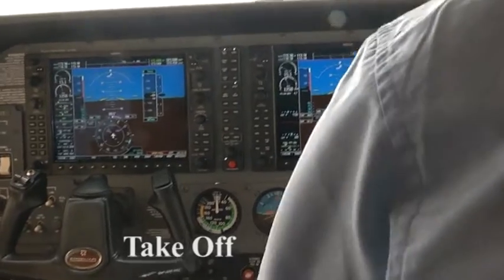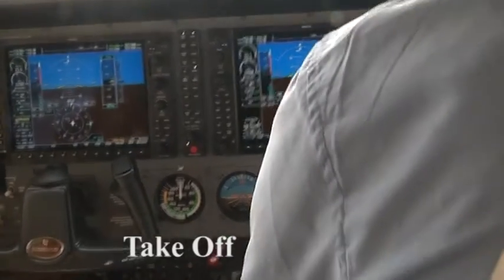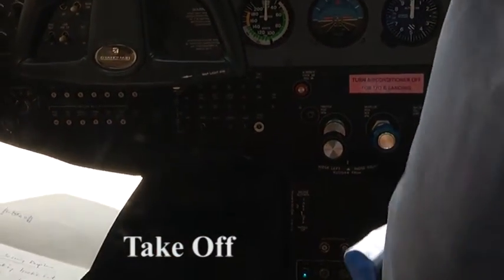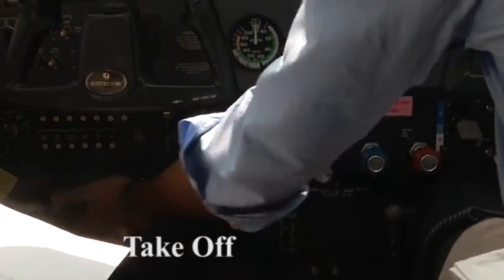Flaps set for 10 degrees, elevator trim set for takeoff, rudder trim set for takeoff. Fuel on board. Fuel selector is on both. Fuel is being drawn from both the tanks.